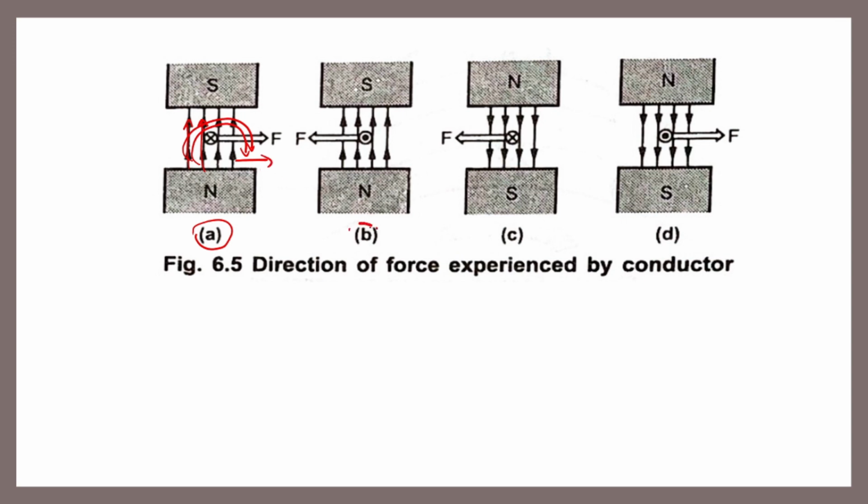Whereas for letter B, the same magnetic field, the same as before, the only thing that changed is the direction of your flux. Meaning the dot is the direction of current towards you. Okay, the thumb faces you, and your four fingers are going counterclockwise. If you try to look at it, there is gathering of flux going on on the right side, whereas on the left side is cancellation, so it is opposite to our magnetic field flux. So since there is gathering of flux on the right side, the direction of the force is going to the left. Okay? So our force is going to the left.